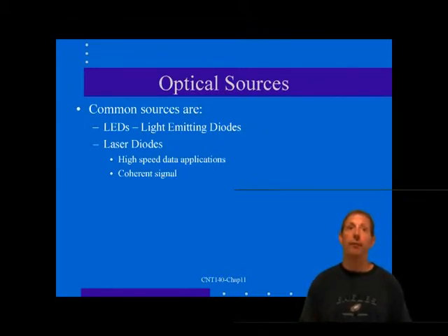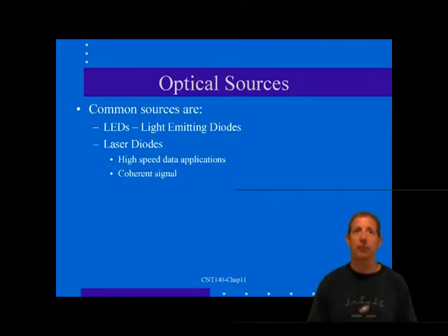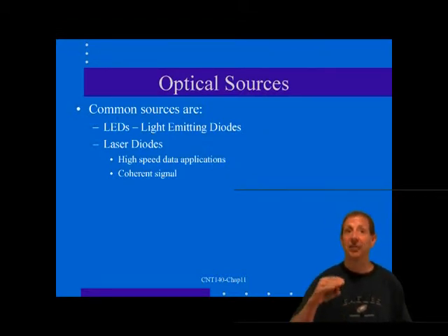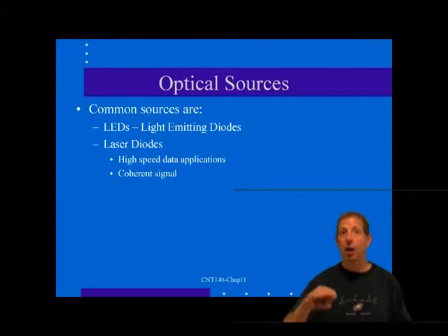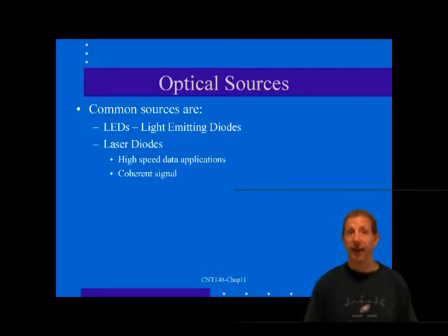In a single mode fiber environment, the laser source works flawlessly. Its highly collimated beam of light is easily aimed right down the center of the narrow single mode core and propagates in essentially a single mode of transmission with all the attendant advantages.